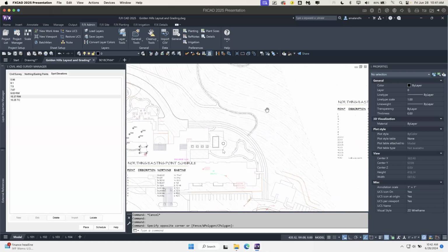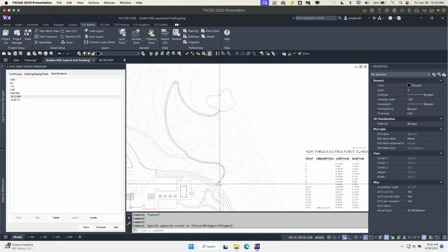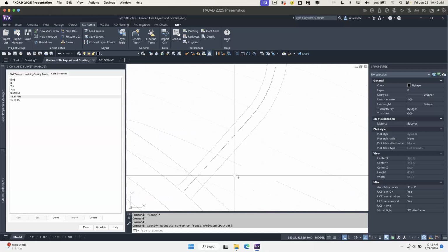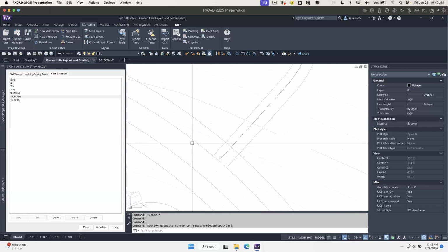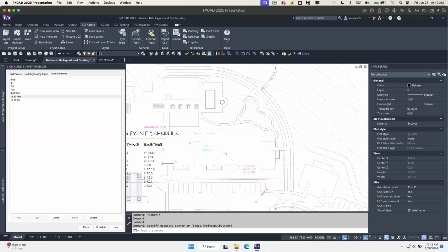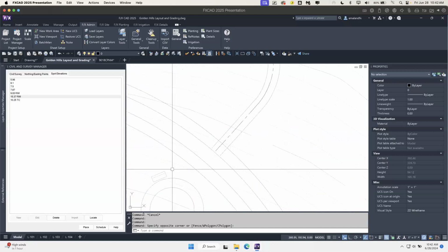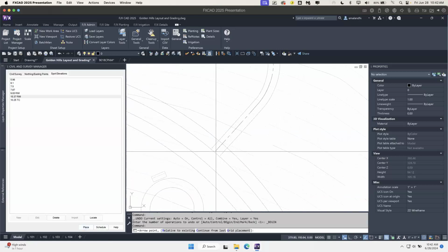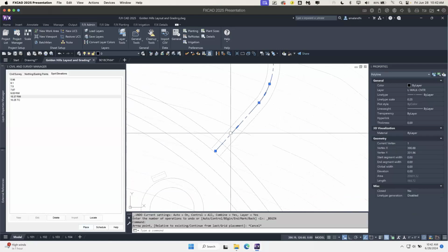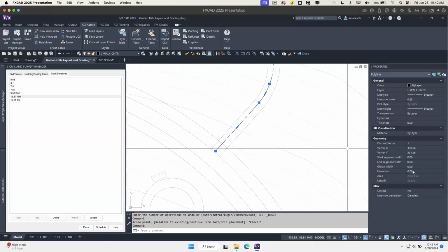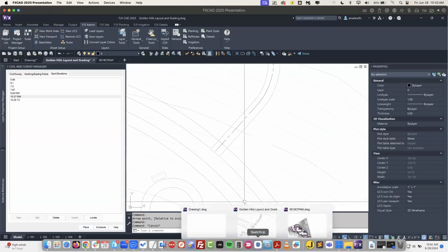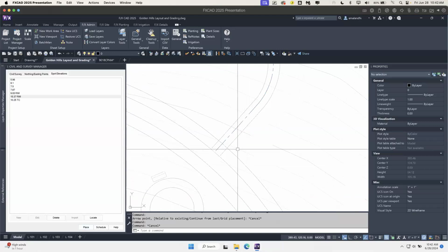So let's go over here to this walkway going all the way up a slope, and see some more powerful tools that you have available in here. So one other thing it can do, so far we've clicked it down and typed in the elevation. You can also go in here and do a new one, and you can snap to an elevation. Now, this polyline I've drawn here is actually at a 0 elevation, but like I told you guys before, these polylines are not. They have elevation.